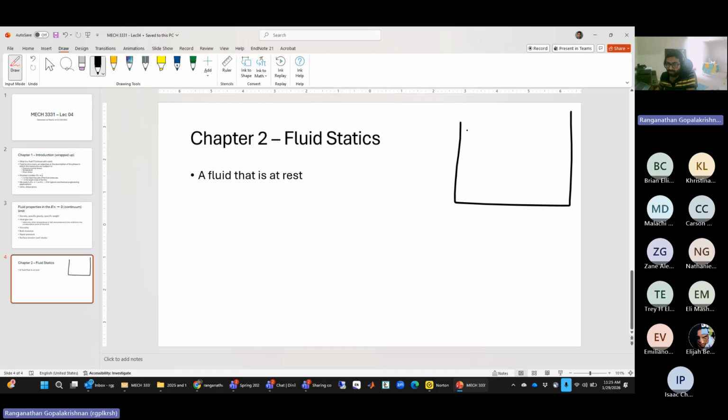So you have a fluid, could be, let's say, a liquid, and this liquid is not moving anywhere. It's not flowing. There is no shear. And what does that mean? The molecules that are going around, they have their random motion. They have all kinds of velocities in every possible direction and magnitude, but they have roughly statistically equal and opposite numbers, so that the fluid as a whole is at rest, but the molecules are in constant motion.